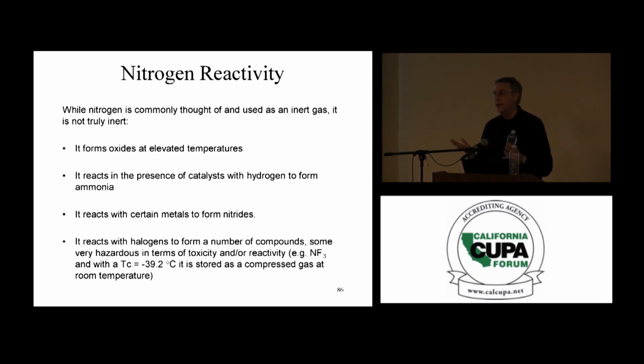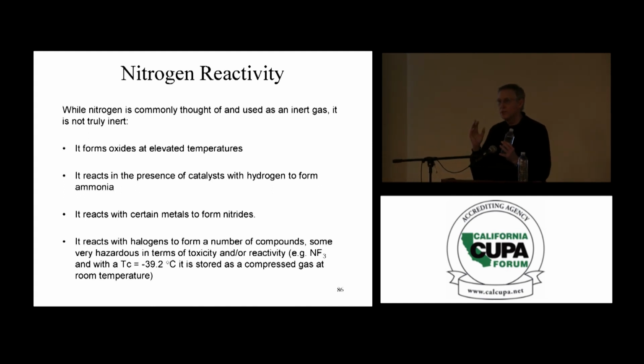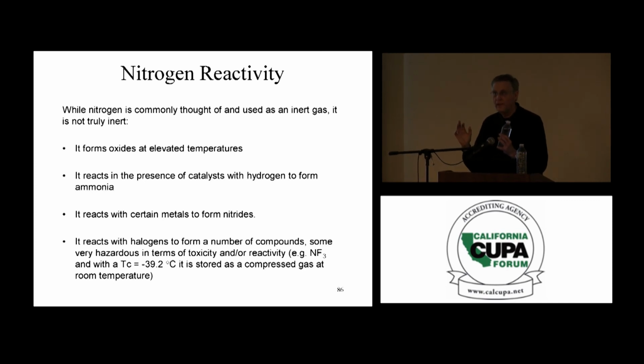So you have the liquid nitrogen at cryogenic conditions in a container that's rated at 250 psi. It's well insulated in the dewar, in the vacuum jacketed vessel. But as it vents, or as it heats up, over a period of time, every now and then it will vent. Sometimes those vent valves can stick open, they can freeze. And what happens then, you get a large discharge of nitrogen vapor.